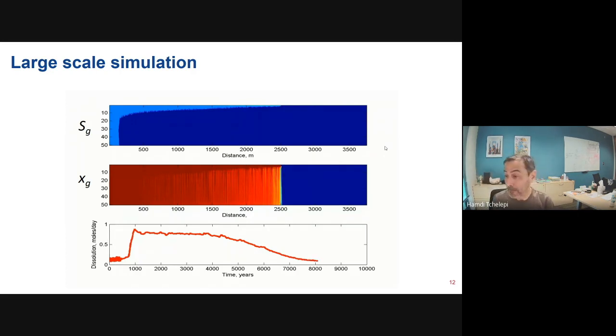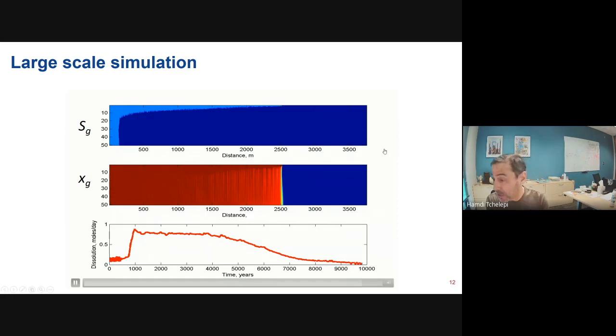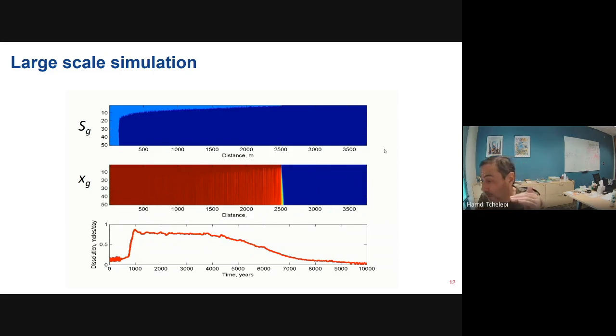And you can see that you can get a favorable set of conditions where the gravity current of what you injected gets completely arrested. It's no longer moving because the CO2 that used to occupy the gravity current has done two things: it has either dissolved into the underlying brine or has been trapped as a residual phase in the back end of the current. And this is exactly the kind of scenario that you would want, say, in a large-scale aquifer, where you cannot guarantee that the aquifer is structurally containing the entire system.